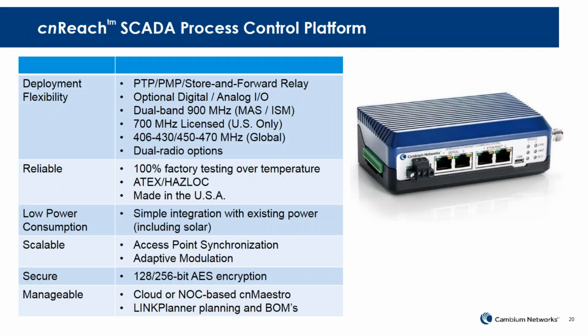So the things that are important when you build a wireless system for process control, I would just hit these at a high level, but you need to have flexibility. Remember I mentioned that you don't know exactly where these locations are going to be ahead of time. So you need a system that can operate in different ways, whether it's point-to-point, point-to-multipoint, in a very harsh environment, or depending on what frequency you want to use, you might have access to different spectrum or different channels to use.